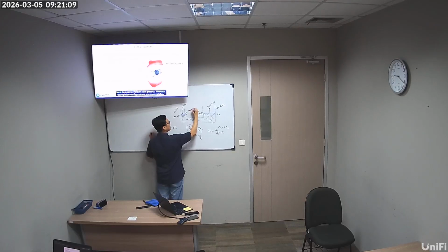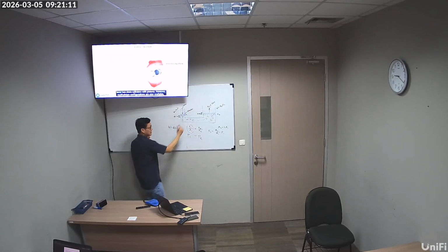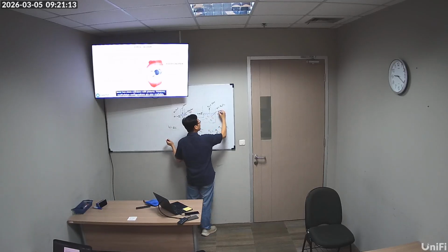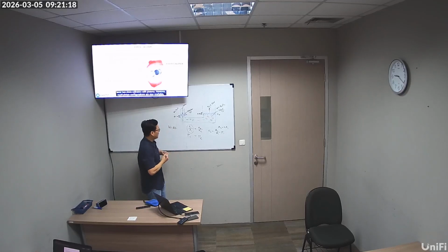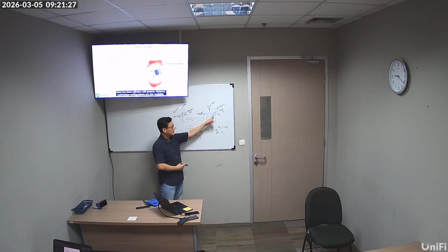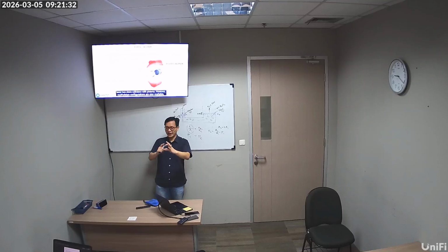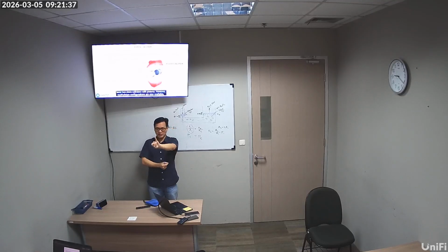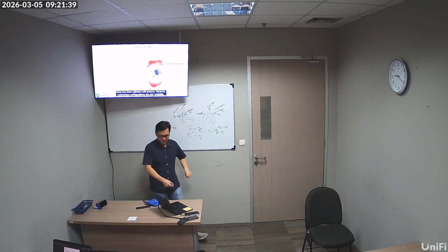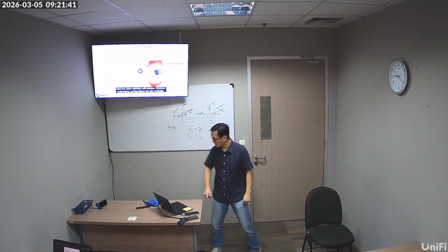master, this is the one that you press, so master cylinder, and this is called slave cylinder because it's the one that is being moved. In the case where you want to multiply the force, which is often the case, the master cylinder will have a smaller piston and the slave cylinder will have a bigger piston. As you can see, your brake is usually about this big of a piston, and your master cylinder is only like a finger size diameter.